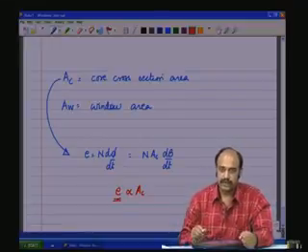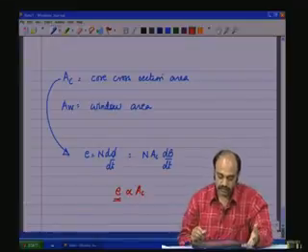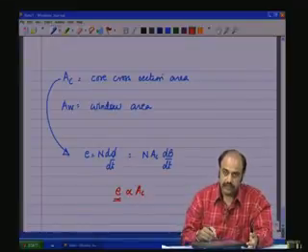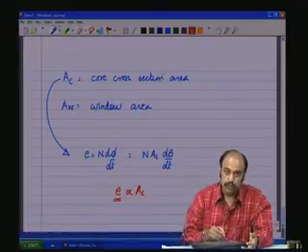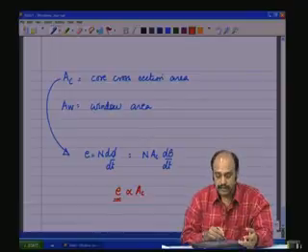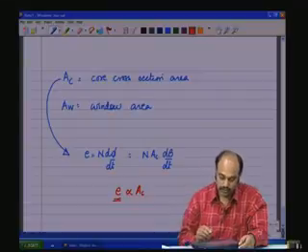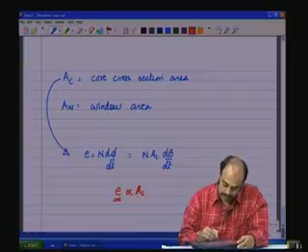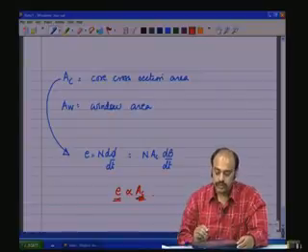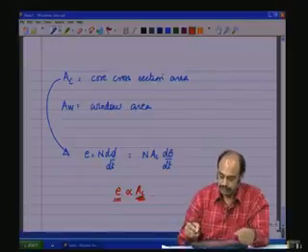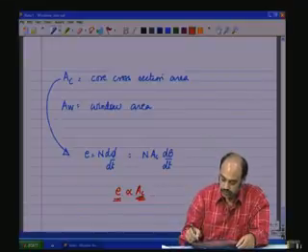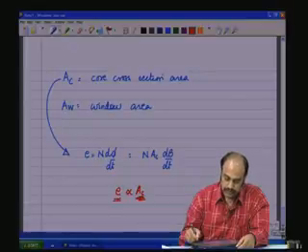How much voltage it can withstand, beyond which the transformer saturates, because beyond which the volt second product will exceed the flux density capability of the core and the core will saturate. So, AC will tell you how much voltage a particular core can withstand.